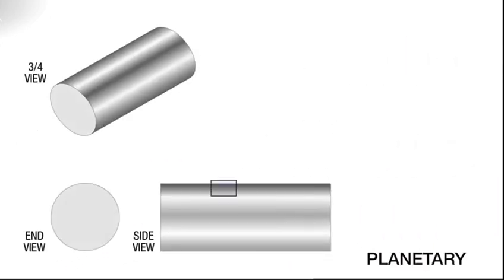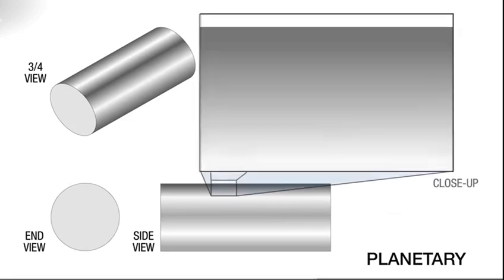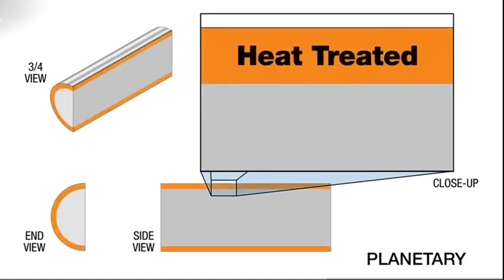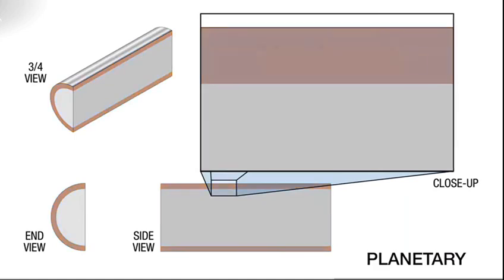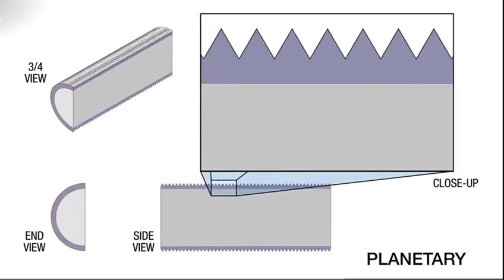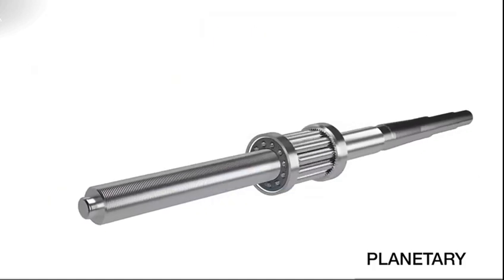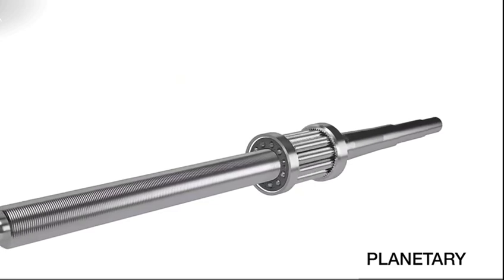Tolomatic manufactures the planetary roller screw design, where first the metal is hardened through a heat treatment process before machining the threads. The hardening process changes the microstructure of the material to increase its strength and hardness to a specified depth that is greater than the eventual depth of the threads. This process of significant heating and cooling the metal can distort machine features, which is why the planetary roller screw grooves are machined after the hardening.